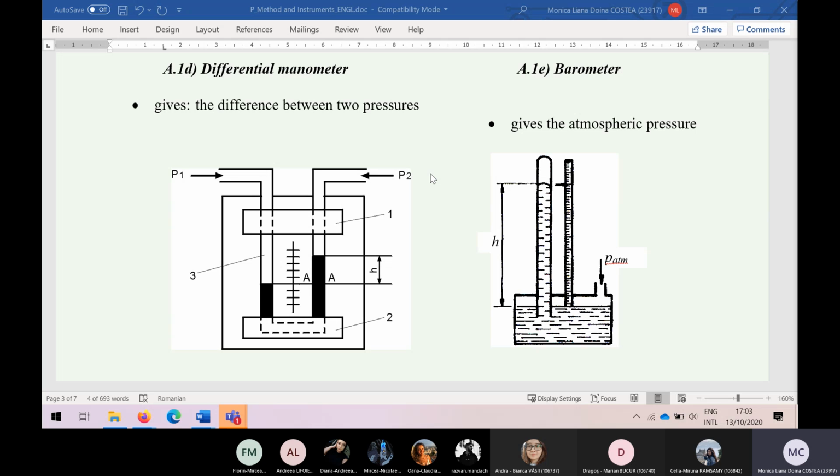Yes? But if you think that P1 could be whatever, either manometric or vacuumetric, and you express it as absolute pressure with B involved, and P2 the same, when you do the difference, B, the atmospheric pressure, will disappear, and you will remain only with this information, rho g h, as absolute pressure. Okay, so be careful.